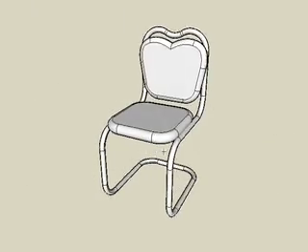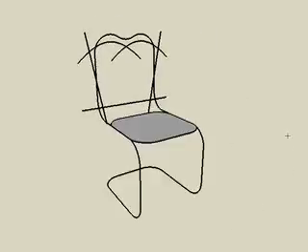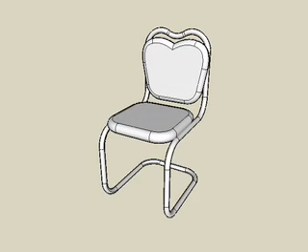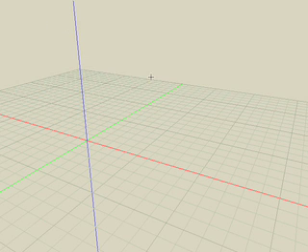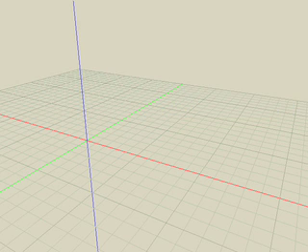Let's conclude this tutorial with a sample project. We'll recreate this chair by sketching the shape as 2D and 3D lines first. Then we'll reshape those lines into three-dimensional solid objects. Let's begin by sketching the frame of the chair first. Select the Vector Line Drawing tool. Select the 2D surface icon. And we'll turn Grid Snap on.